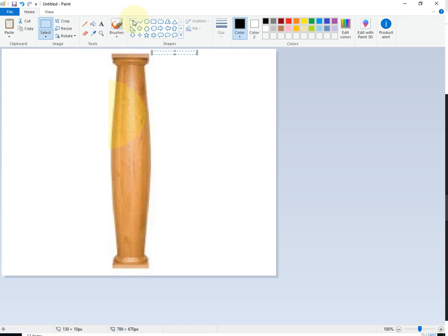What we have is the two reference lines on the top and bottom, or the reference levels, and then we're going to probably create a reference plane for the thickness of the top and bottom as well. We'll create another reference plane for the height of this little detail. Then we'll probably have a reference plane going through the center, which we'll probably need for doing some geometry.